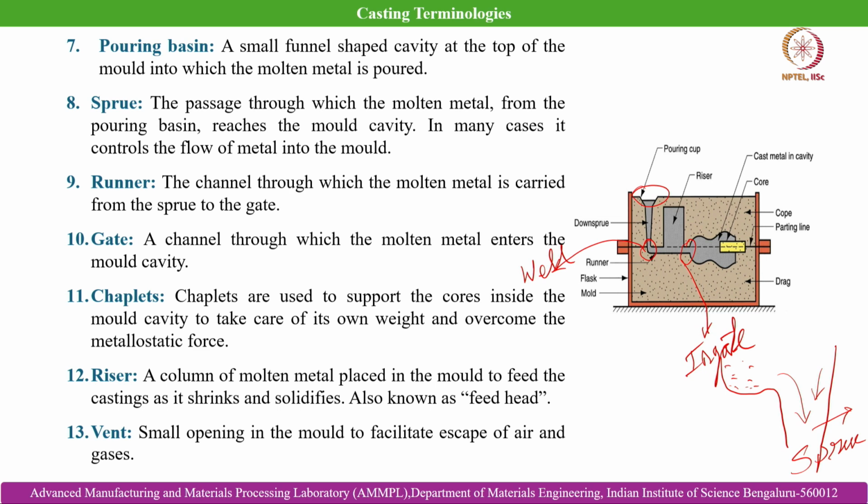And then chaplets. Chaplets are basically used to support the cores. Like I have already told you, this is the core. That core has to be supported with the help of chaplets, so that it can take care of its own weight and also overcome metallostatic forces.